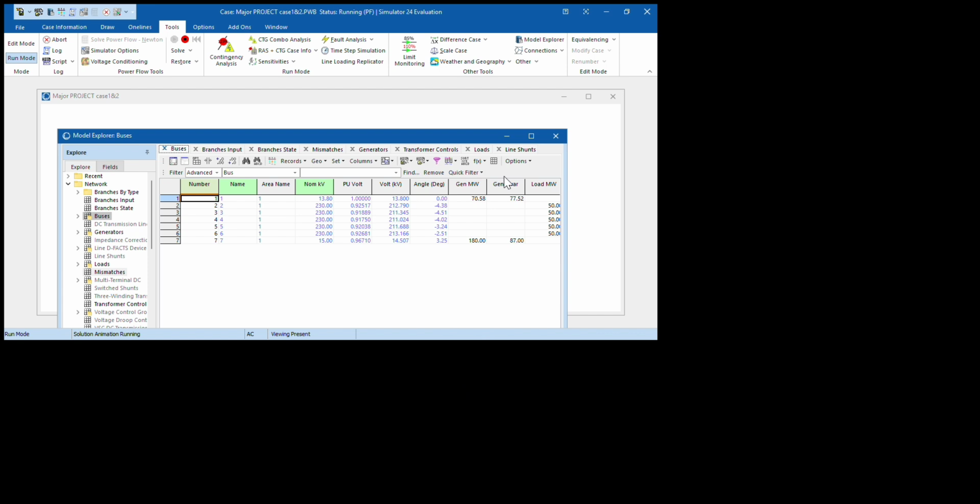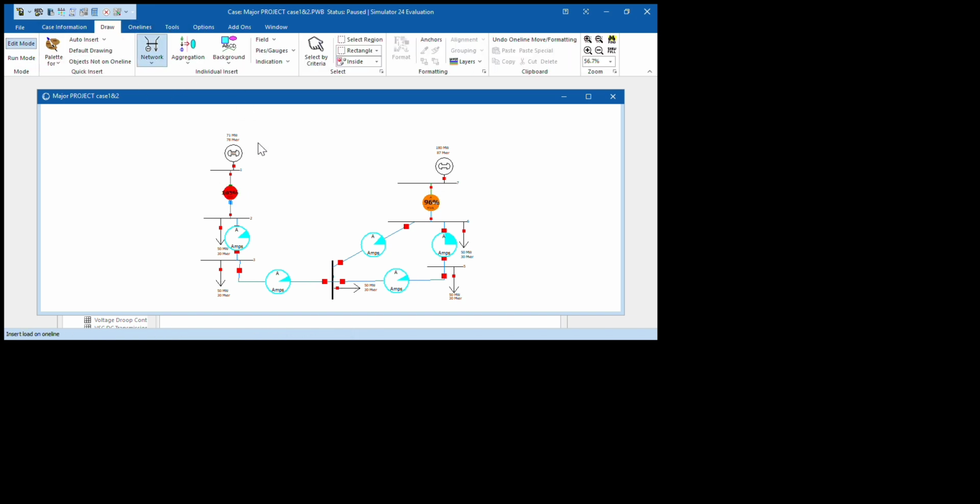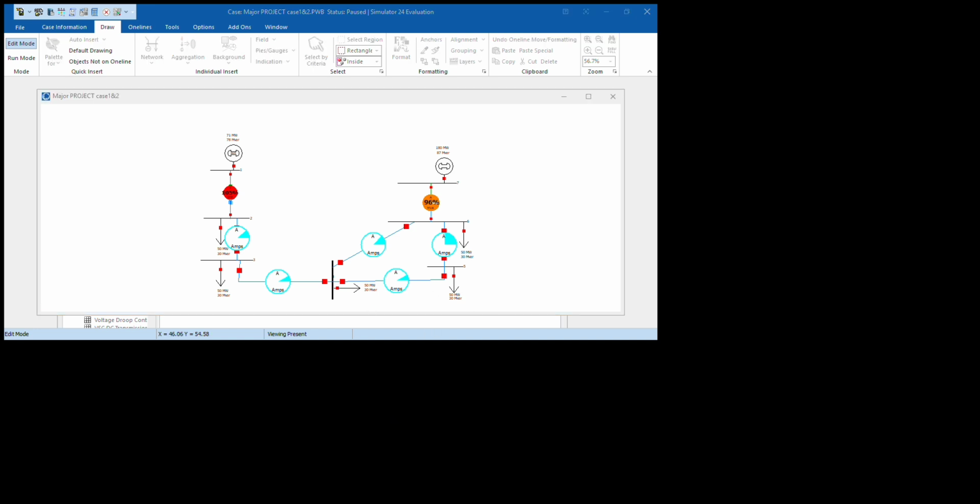So the method I use is, first we have to stop it. I will add a switched shunt or capacitor at bus 4, because the function of the shunt capacitor is to support the voltage and reduce the reactive power, but we do not know what value we should start with, so we use the trial and error method by starting with 40.